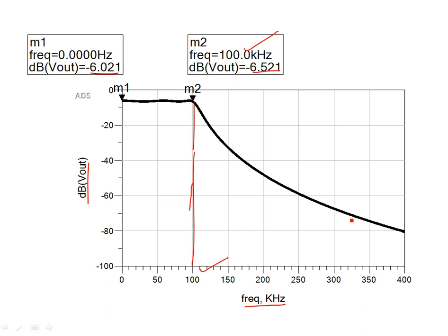There are no ripples in the transition band, neither are there any in the stop band. There are ripples, but they are hardly noticeable because the ripples are 0.5 dB, and on this scale 0.5 dB is hardly discernible. This is a type 1 Chebyshev filter response, because the ripples only occur in the pass band. Okay, so you can see this is the procedure for how to design a low pass filter.